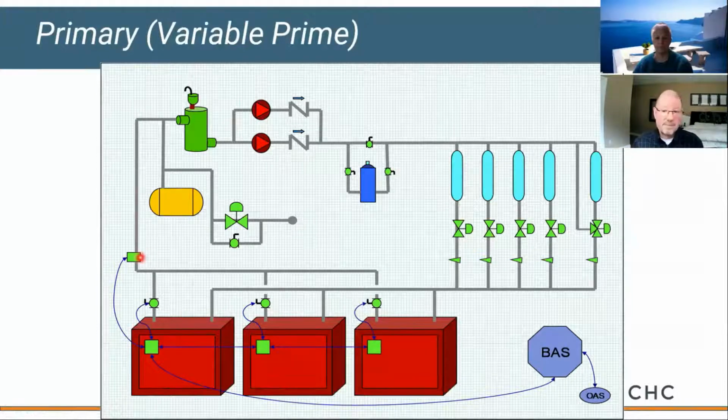Pretty straightforward. Okay. The other thing that's very important about these, you can't close them all. Even if the boiler's not firing, you have to leave at least one of these valves open so that we have flow that comes back from the system and can continue out here through our system pumps. Okay, all that's controlled through the boiler control panel. It knows to leave at least one valve open so we don't run into some problems.